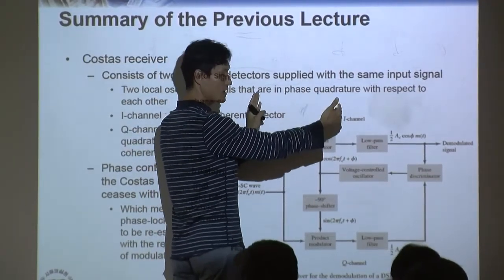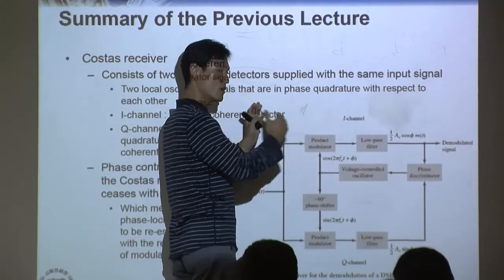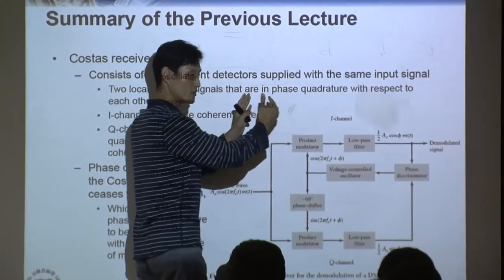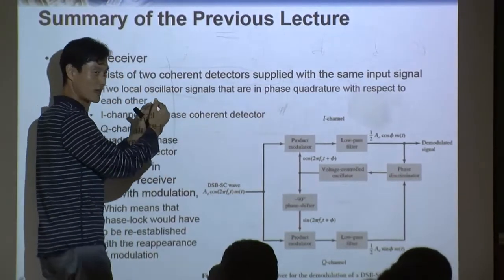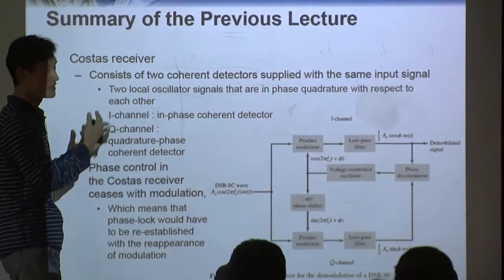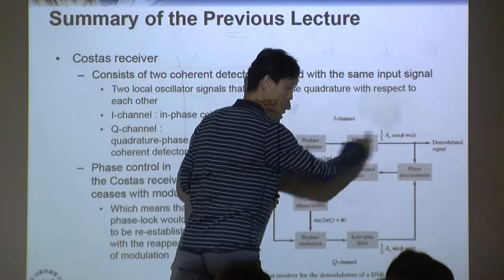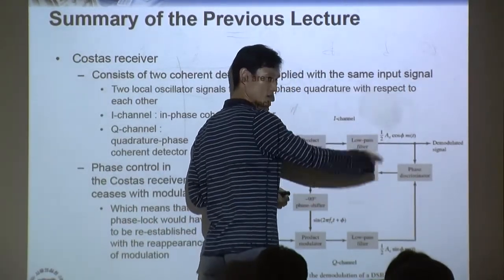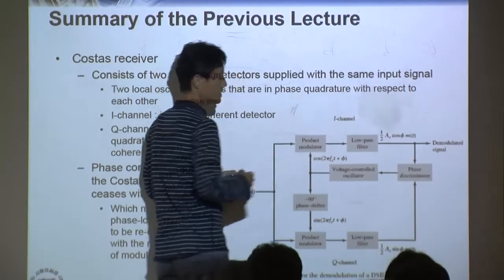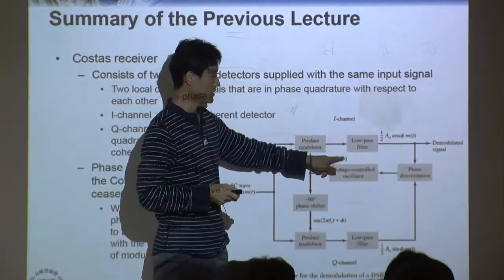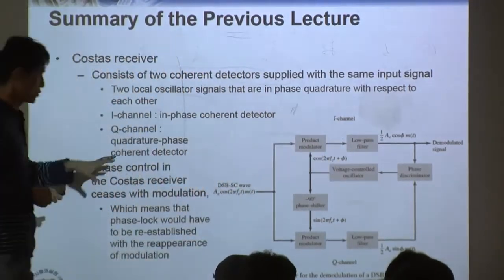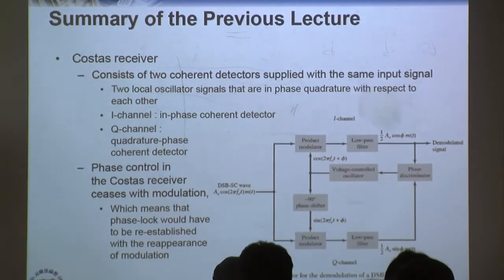Or maybe if your phase is a little bit ahead, then you want to make the frequency a little bit slower so that it slows down a little. And then eventually it'll be matched, right? So that way you're doing feedback. This keeps running, and little by little you correct it. Eventually, this phase becomes 0. So that's what we do in the Costas receiver.